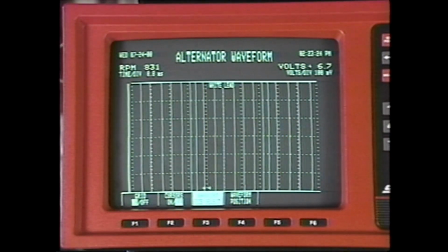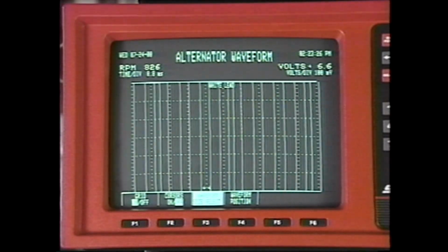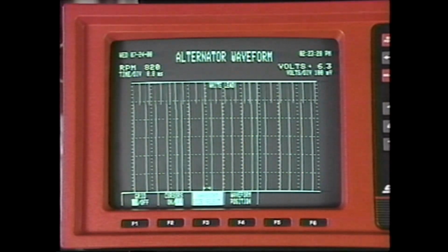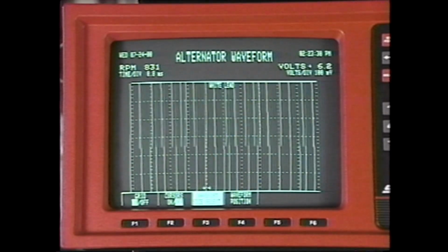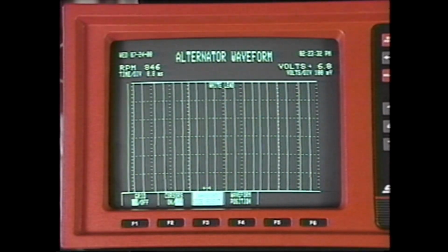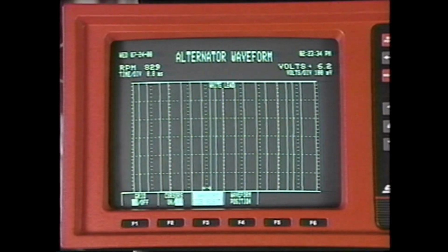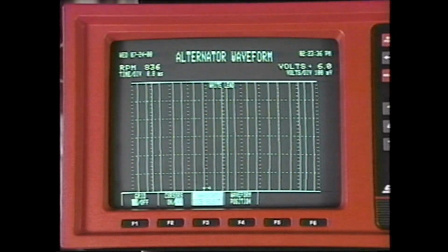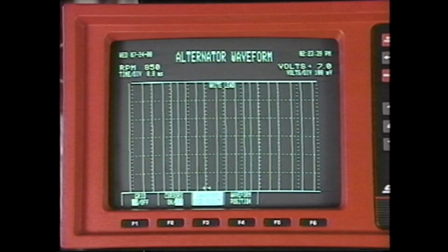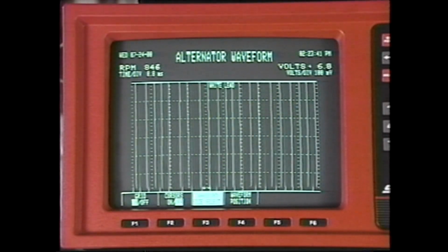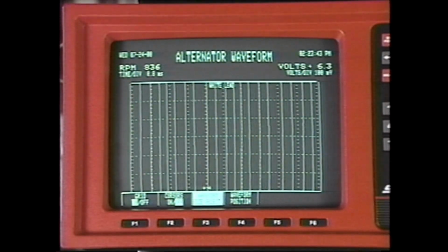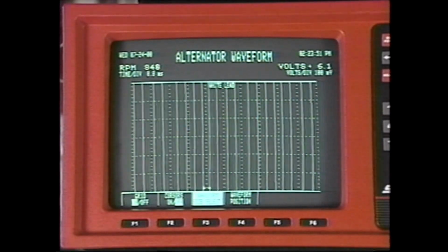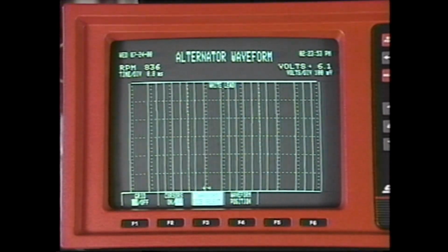A diode test requires a signal from the regulator terminal, such as the number 1 terminal on a GM Delcatron. If a diode trio is bad, there is a significant voltage drop. Instead of ripple, the pattern is expanded beyond the capacity of the alternator screen. Use the voltage or lab scope screen to examine details of the number 1 terminal.